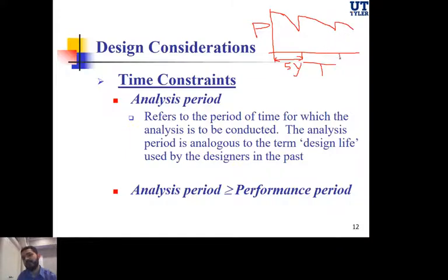years, let's say this is here 7 years, and this here the minimal, let's say seal coat, is going to last for 3 years before it reach perfect failure or terminal failure. And now at this point we need now to rip off the entire structure and do a major reconstruction. So in this picture here, we can understand the two things, analysis period and performance period.